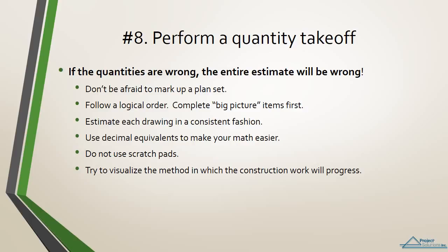Don't be afraid to mark up a plan set. It's not a museum piece, and if your firm is serious about performing the work, you will need multiple copies anyway. Use colored pencils to help you divide up the elements on the drawings. Follow a logical order. Complete big picture items first. Estimate each drawing in a